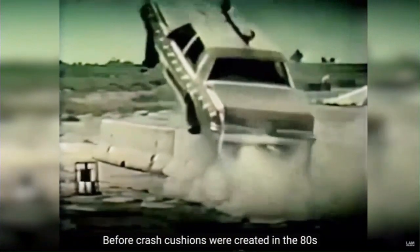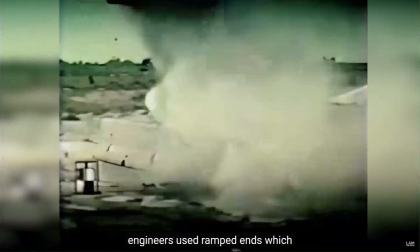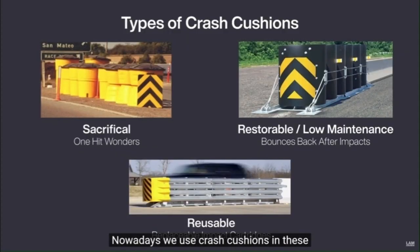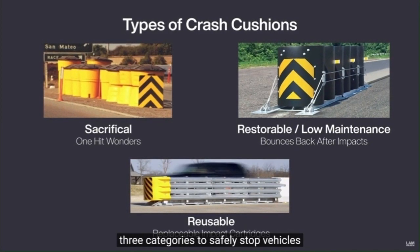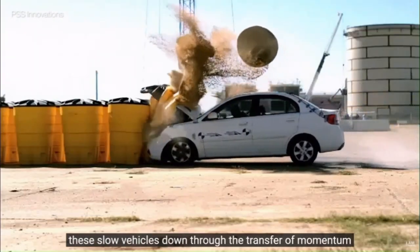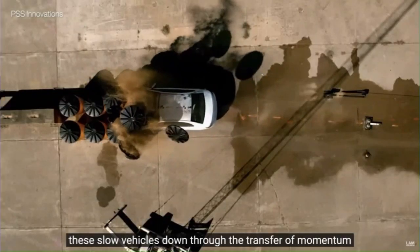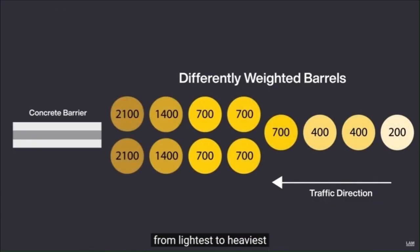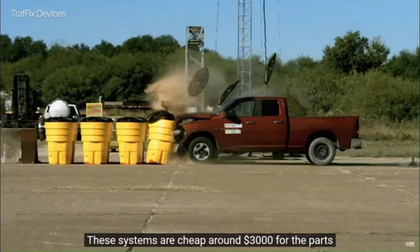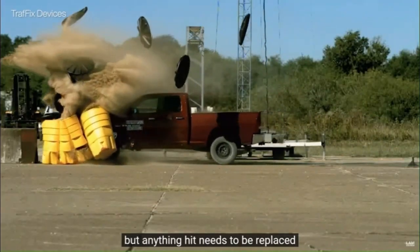Before crash cushions were created in the 80s, engineers used ramped ends, which produced dramatic and dangerous results. Nowadays, we use crash cushions in these three categories to safely stop vehicles. Starting with sacrificial systems like sand barrels, these slow vehicles down through the transfer of momentum. They're arranged by weight, from lightest to heaviest, so small vehicles can be gently slowed down and still protect heavier ones. These systems are cheap, around $3,000 for the parts, but anything hit needs to be replaced, and it's messy to clean up.